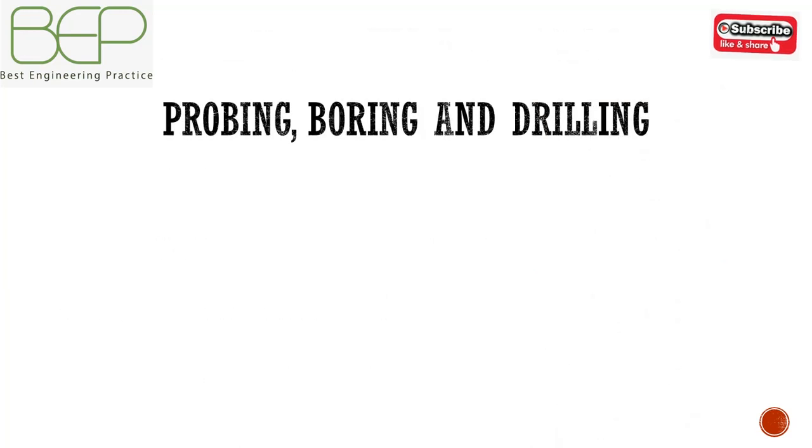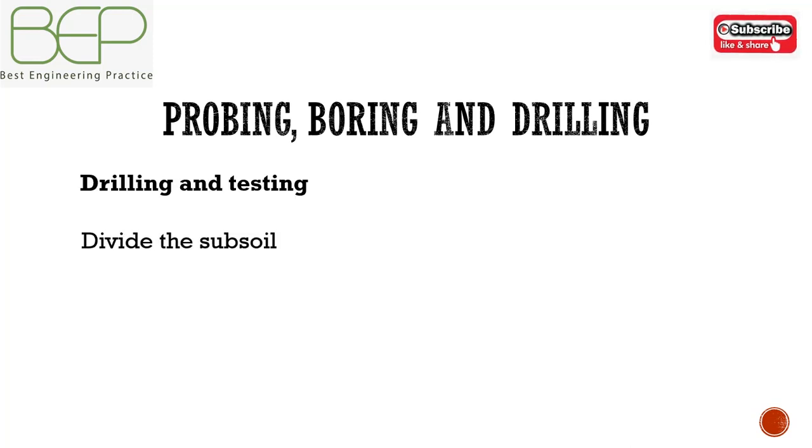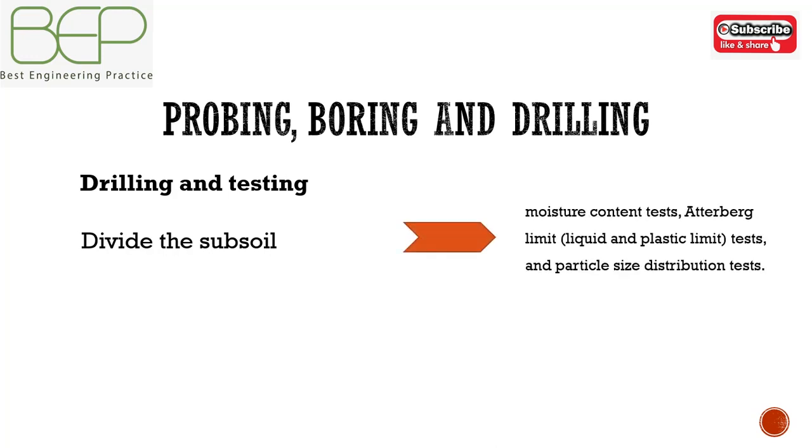The objectives of site investigation, drilling and testing are threefold. First, to divide the subsoil into simplified soil types or groups. Soil grouping and the assessment of the soil variability within each group is normally carried out on the basis of visual sample description, moisture content, Atterberg limits tests, and particle size distribution. These last three types of tests are often referred to as classification tests because they are used to classify the soil into groups of materials which are expected to have similar behavior.